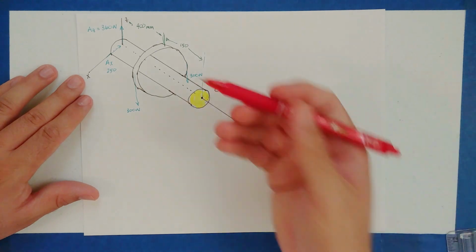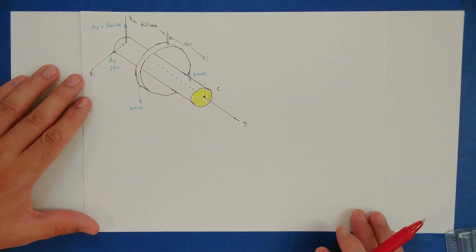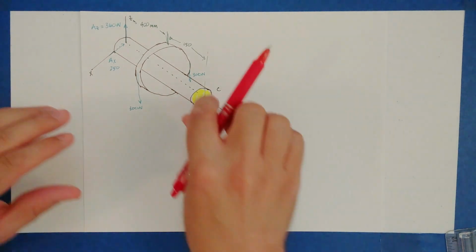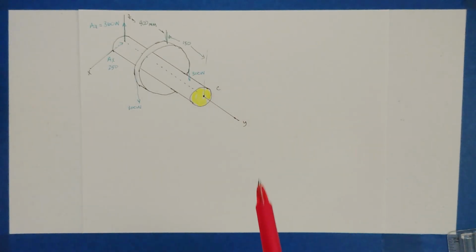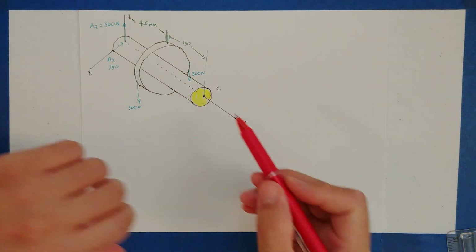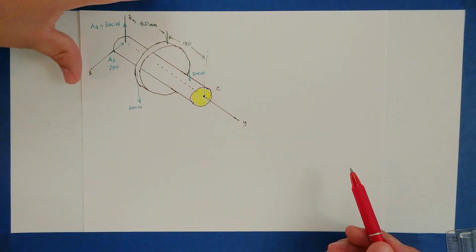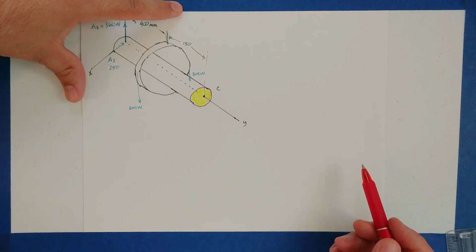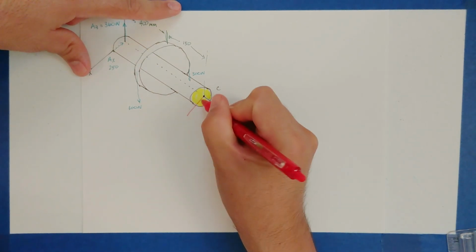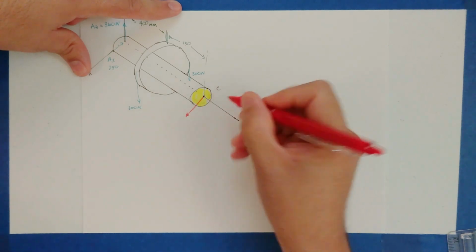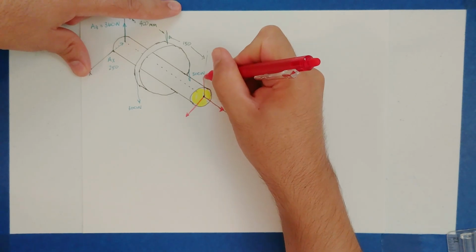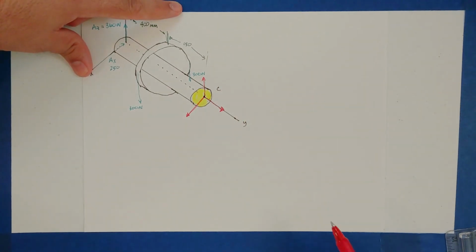So now what we have to do is cut it, and figure out the internal load. When we cut, this was not welded, but it was part of another thing. So basically what we have is a fixed connection, which means we can have up to 3 forces and up to 3 moments acting at point C. Since I teach statics, I like to think of these as a force in the X, Y, and Z. So there would be a force here along the X, a force here along the positive Y, and then a force along the Z. From solids, we know that these forces